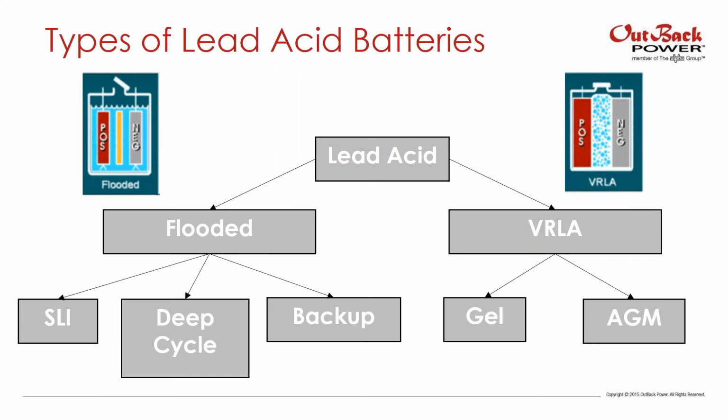Like I said earlier, if you decide to use your deep cycle batteries for, let's say, a backup application, then you're not cycling them very often, and they want to be cycled, so you could really impact your battery life. The same goes for using a backup battery in a daily cycling application. So it's really important to qualify the application.